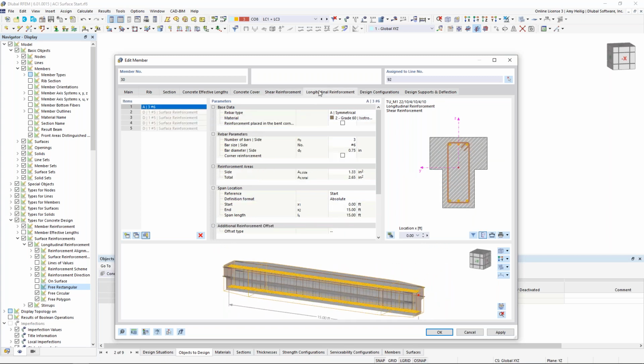For the longitudinal reinforcement, notice we have some grayed out options here. So what does this refer to? Well, if I take a look along the length of the member, we can actually consider automatically the surface reinforcement. Remember those number 5s at 12 inches on center that we defined? You can see them displayed here in the effective widths or the flanges. Well, we can also turn this off and manually apply reinforcement as well, which is what we'll be doing today.